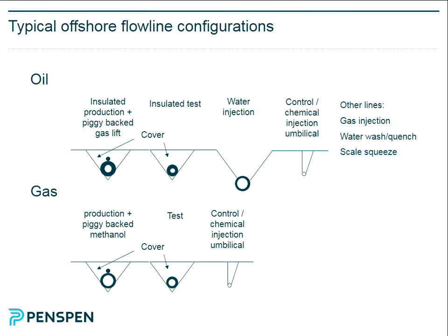It's for reducing the pressure drop in a well. The way it works is it injects gas at some point below in the well bore, and that aerates, in fact gasifies, if that's the word. That intentionally creates multi-phase flow in the well, and reduces the density of the fluid by introducing gas. That allows the well to flow more effectively.